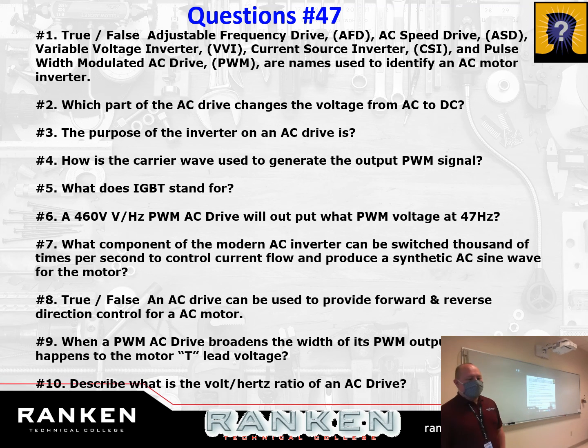Questions? Comments? Describe what the volts over hertz ratio is. It matches the frequency to the voltage output so that you don't overcurrent the motor, essentially. It lowers the voltage as you lower the frequency, or raises the voltage as you raise the frequency.